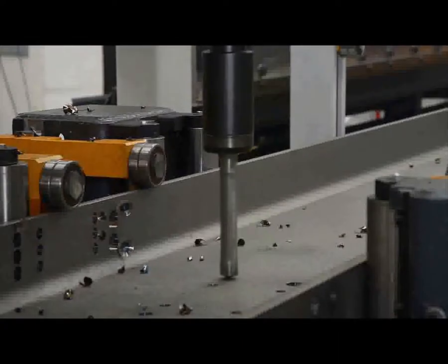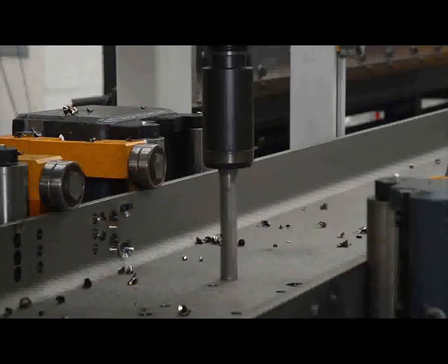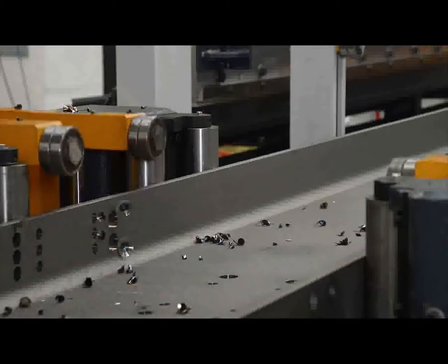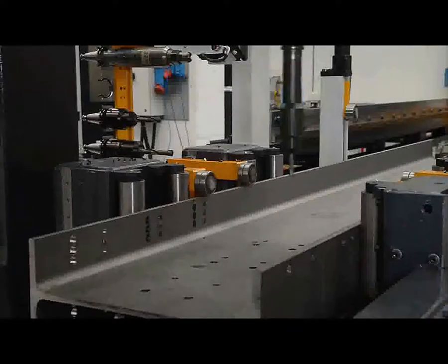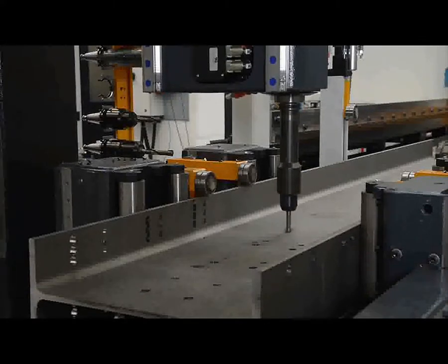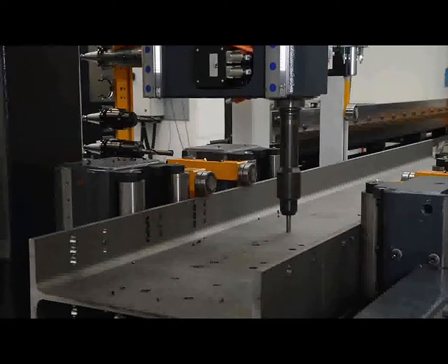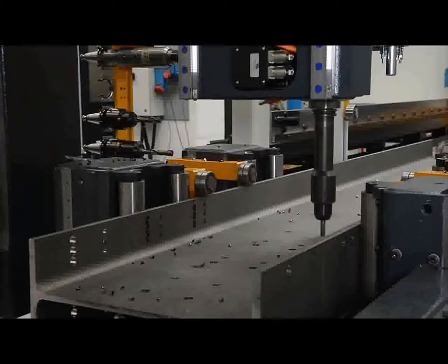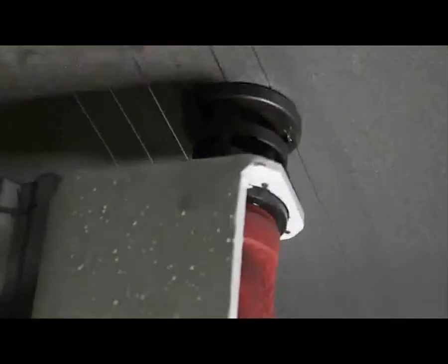Again, the instructions for drilling, tool changes, different size holes. When it's doing the timings from Tekla as well into Steel Projects PLM, it knows it's quicker to drill a smaller hole than a larger hole, so it takes all that into consideration as well. There we are. And again, scribing can even be on the underside, so the layout marking can be on all sides. So it's real true three-dimensional information.